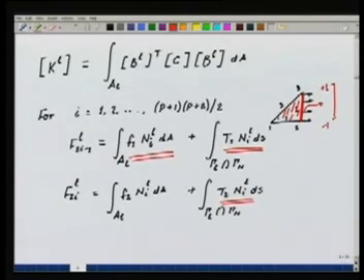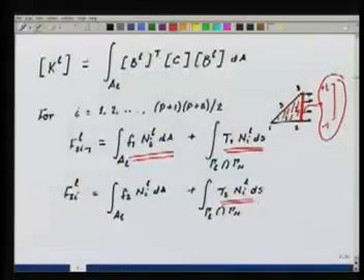Okay, transformation we should be able to do it very easily. That is, take this edge to this edge, get the integration points, because this is where I know the integration points, and do the integration by summation there. Okay, so this has to be done as a separate loop in each element over the three edges of the element, and you have to carry the information about which edge of the element lies on the domain boundary and which does not.